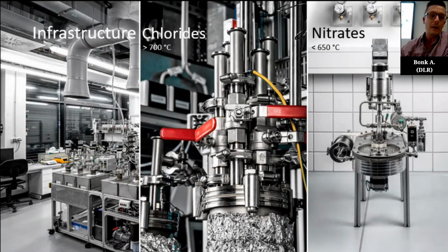And one is the state-of-the-art nitrates, and you've been seeing one temperature maximum right now, which is 565 degrees. Well, our goal in the past was to push this temperature limit to higher limits for multiple reasons. One is if you increase the delta T in your energy storage system, you have higher storage density in the same volume. The other is if you run a steam cycle at a higher temperature, your efficiency increases. So you would basically create two benefits at once. The downside is stabilizing the nitrates at higher temperatures is a real challenge, and I'll show you in a minute why.